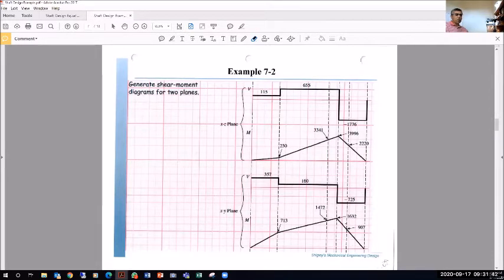So where I have my maximum moment, I'm not looking at a single number at the peak like we did when we had the prismatic shaft, but we are rather looking at the numbers surrounding this area where I have geometric variation because I have a shoulder, and I also have, of course, a fillet at the shoulder, and I also have a key, and I also have a groove ring right here, because all of these may be critical locations. Does anyone have any question about that?